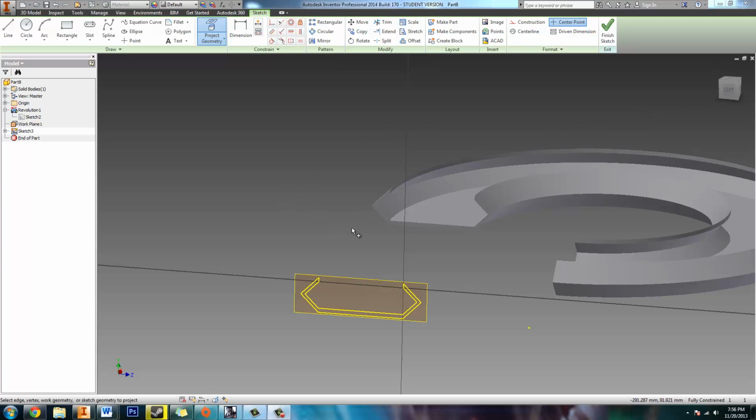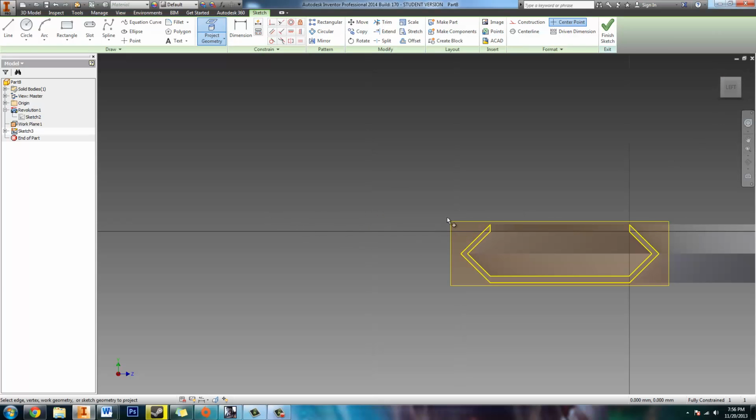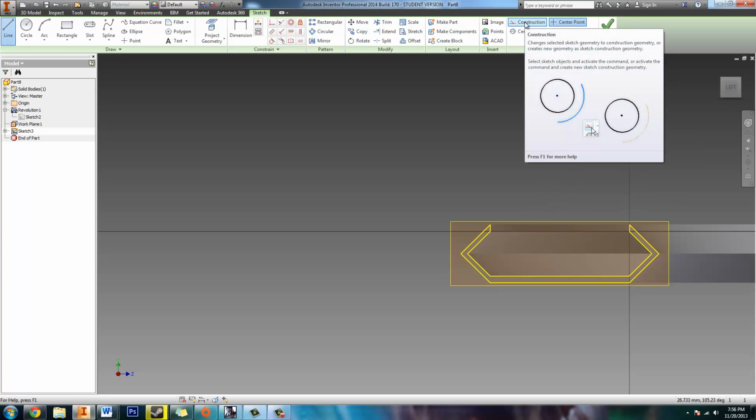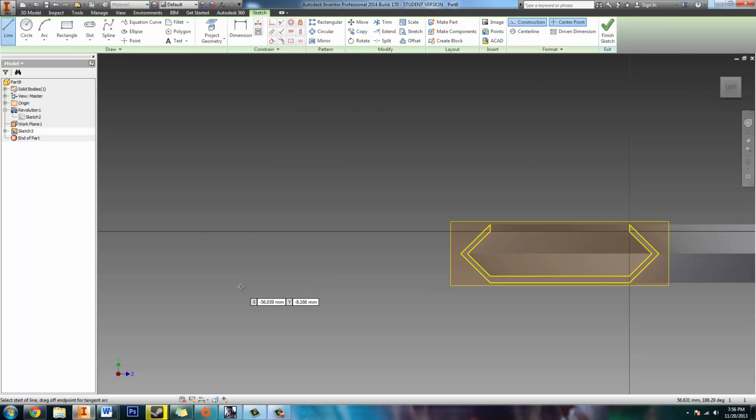Now that that's done, we'll center our sketch by clicking in this top right corner, that panel, and we'll zoom in, and we need to create our center line axis so we can revolve this sketch around it. So select line, and make sure it's a construction line. And again, make sure that those dotted lines pop up so that you know that it's a 90-degree angle to the center point of the sketch. Click and drag up, make it whatever height you want, and then left click and escape. We'll dimension this 40 millimeters from the center point.